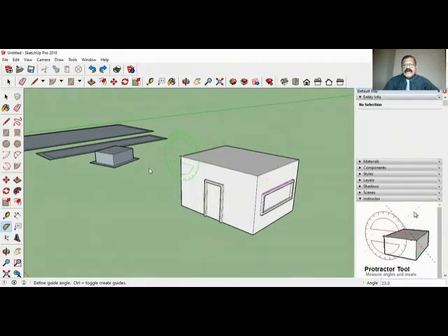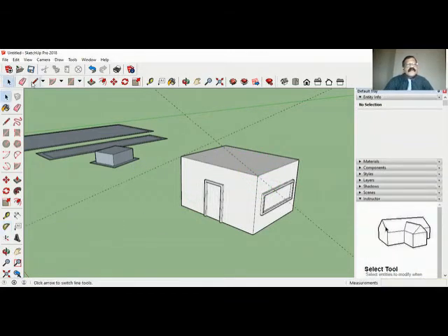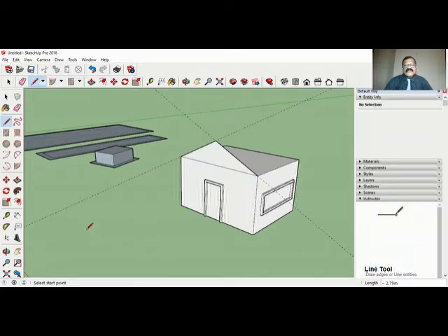You can see one guide is coming. So usually that slope is 26.5 degree. That is what usually we do. Click. So you have drawn 26.5 degree one line here. Now here also, click, come here, this side, click and drag here. And type again 26.5. So this is a slope, standard slope. I will use the line command. So you got a face there.